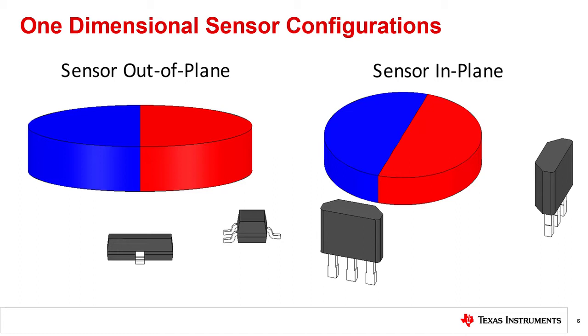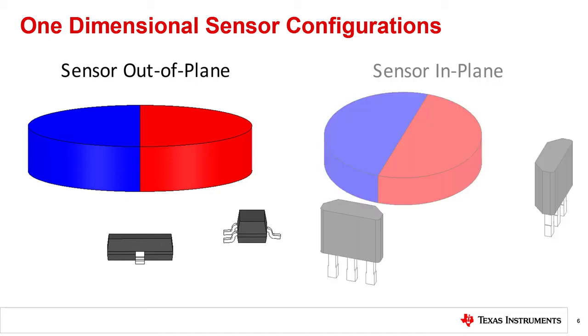Implementing a two-sensor configuration is possible with a variety of configurations. One method is to use two distinct linear Hall effect sensors which are mechanically separated by 90 degrees. With this approach, there are two basic alignment options. The first arrangement uses surface mount devices placed beneath the outer face of the rotating magnet in an out-of-plane alignment. This is sometimes also referred to as off-axis.